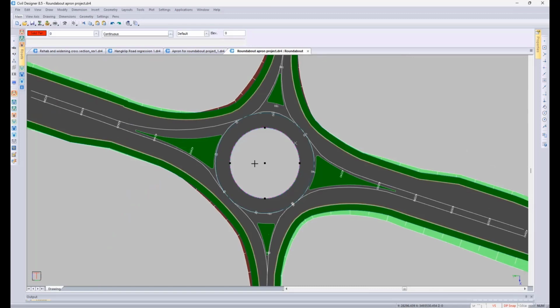Okay, and then I need some geometry lines to position all my PIs. So I'm going to go to geometry line. I'm just going to use tangent to a circle for my first line. Reading the prompt over here, indicate the geometry circle. That's the one I've just created. And then I'm just going to use that. That line's fine. Okay, so it's tangent. That line is tangent to the circle, that geometry circle.